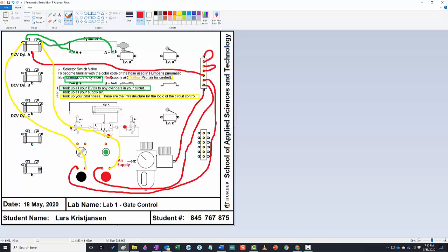Now there's actually a second way to do this. I could have run my air supply into here, and only these two were connected. So I'd have to run another line to here. So if I were to have done this, and then I were to run a line into there, I have 1, 2, 3 available. So I could have done that too, but I just chose to use the one larger open manifold and block these off.